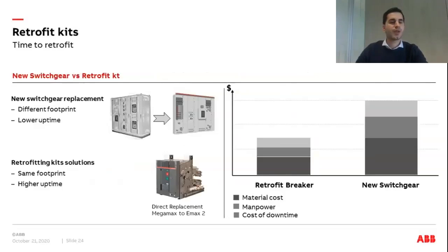Going ahead, why choose retrofitting kits? Why are they convenient? If the switchgear is in a good condition, I mean panels and busbar, choosing a retrofitting kit is convenient because there is a relevant saving in terms of material cost, manpower, and in particular cost of downtime.